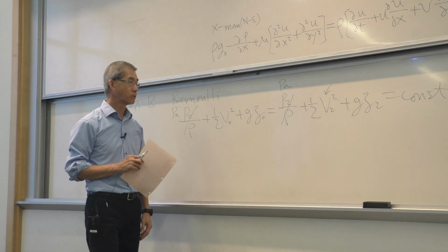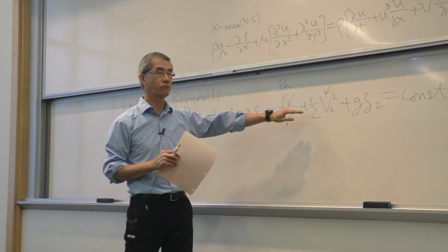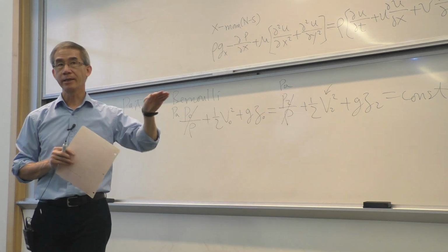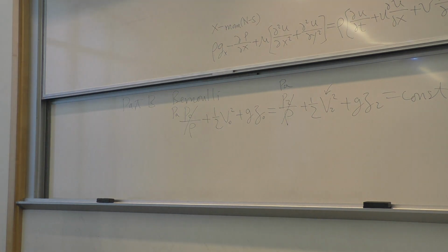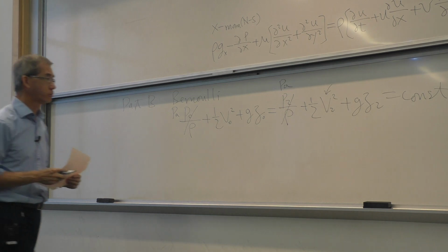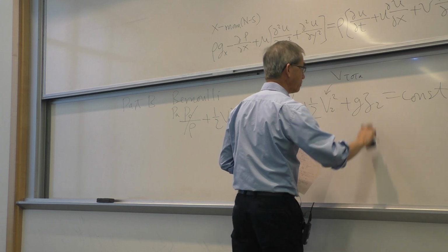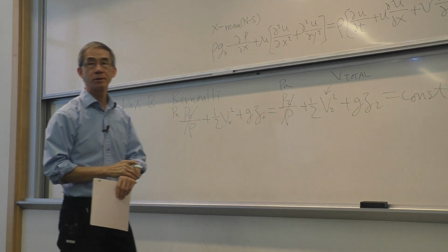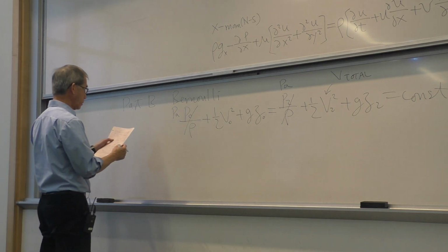All right? So I have my question now for the velocity in the Bernoulli equation. Is this velocity V0 or V2 only in the x direction, or only in the z direction, or the total velocity? Total, very good. Should be very definitively total, because in the Bernoulli equation, we integrate the Euler's equation of which the velocity is the total velocity. So with that, let's apply that to point A.